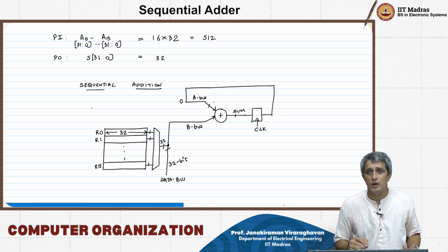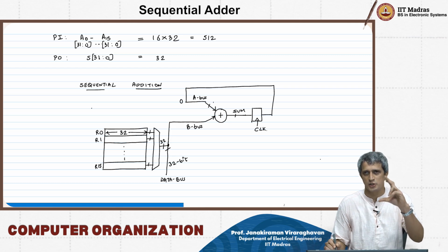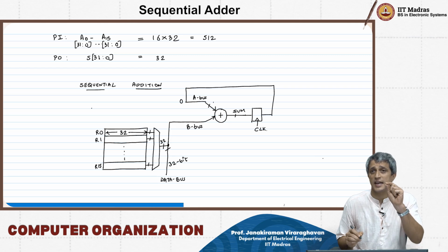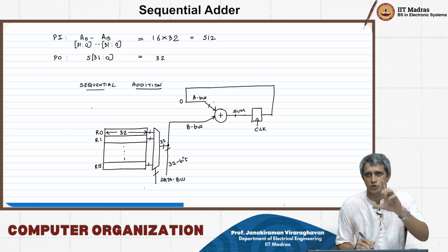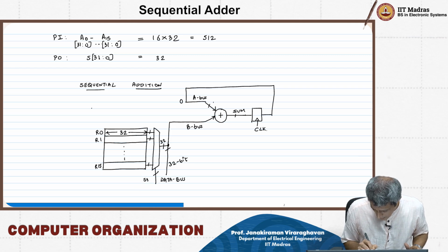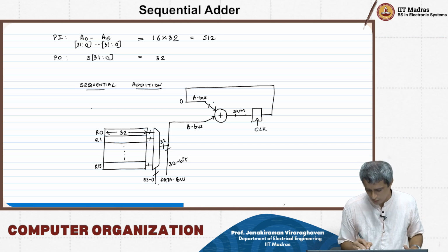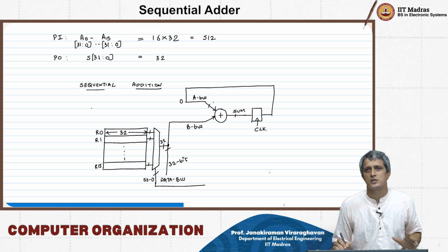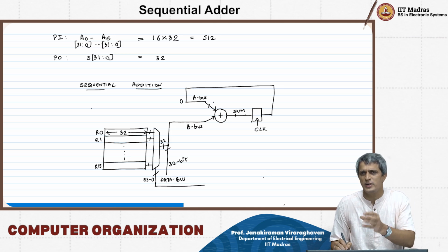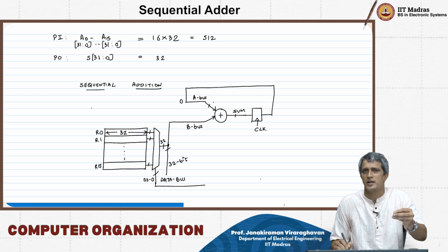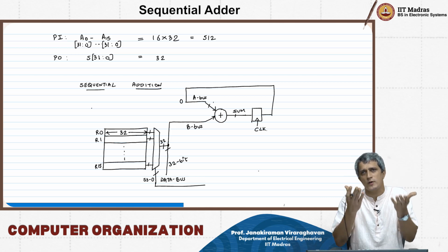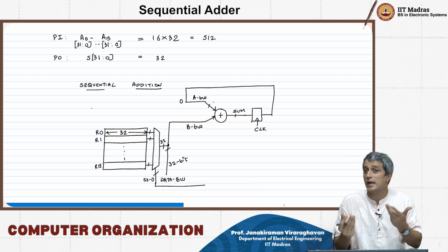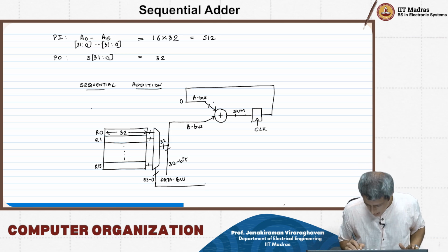Now remember that my registers 0 to 15 need to be selected by a select line of the mux. How many select lines? It is a 16:1 mux. Therefore, I need S3 to S0, select lines 3 to 0. Since the operation that we are trying to do is very deterministic and fixed, that is simply adding numbers R0 to R15, I just need to sequentially go through all the registers. I don't need to go in any random order, and therefore I can basically put a counter here.